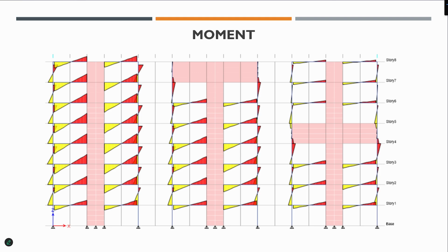So suddenly you increase the stiffness by an order of magnitude, 2 orders of magnitude, by putting them together at one place as an outrigger rather than distributing them on many floors. So that's what we do. We use engineering to beat the math. Like I told you, we take out the thickness from each of the beams and we put a big beam and we get a much better effect, cost saving also, because we save on every floor.